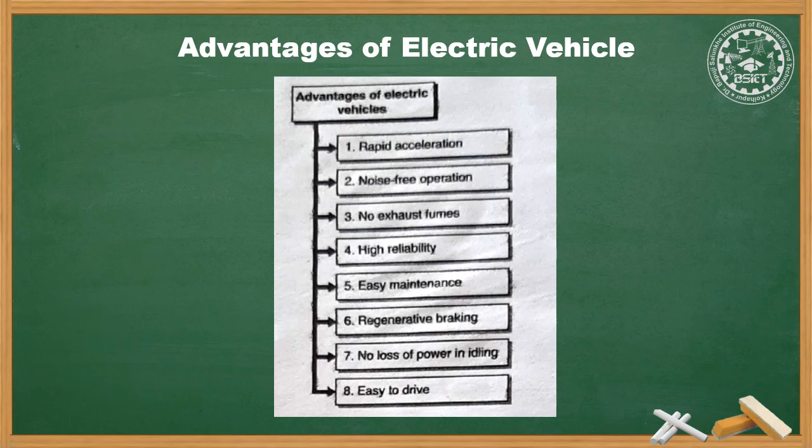Regenerative braking. When we take off the accelerator pedal, the motor becomes a generator, sending the energy of motion back into the battery. ABS brakes are automatically applied in emergency stops. Energy spent climbing uphill is recovered on the way down rather than burning up the brake linings.